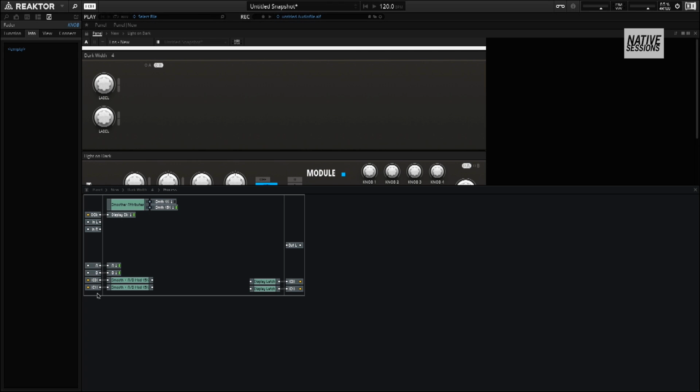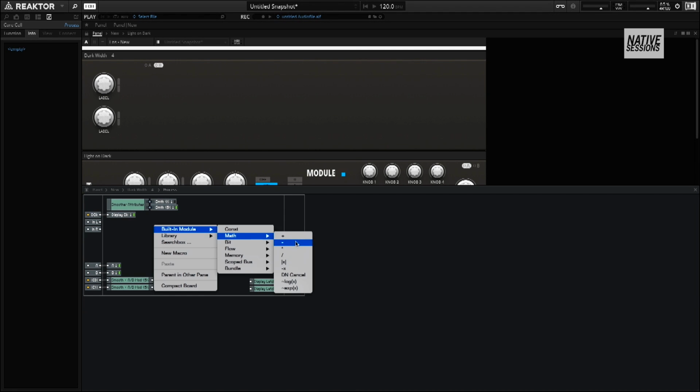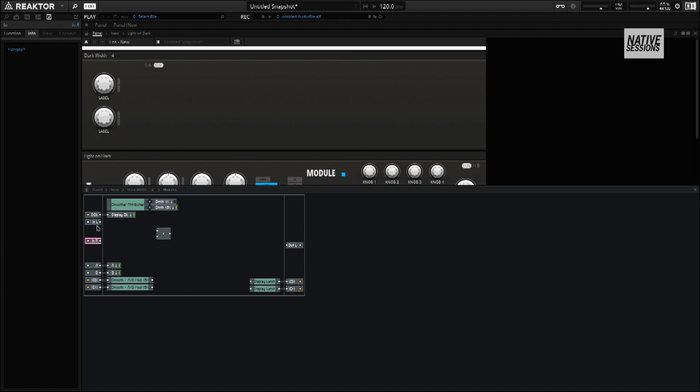These are our modulation inputs. So if I want to change the volume of a signal, all I need to do is multiply the signal by our modulation signal. So I go to math, I go to multiply, I say take input left, multiply it by our modulation signal, output it.